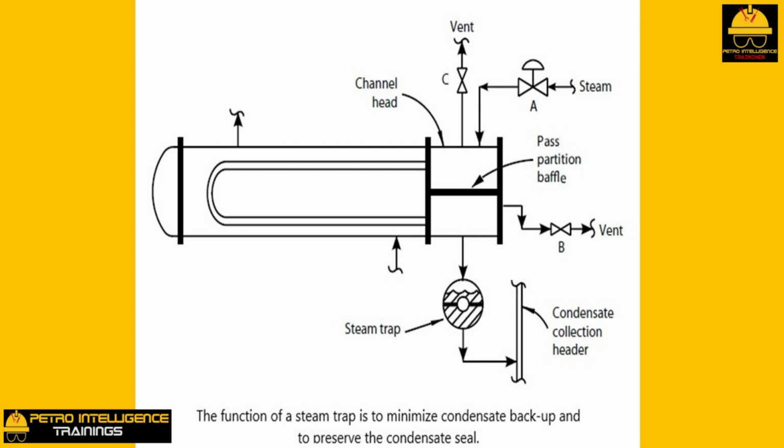The standard is to continuously vent 0.5% of the steam through a restriction orifice to purge CO2. Even if you are producing steam from demineralized water, just a small fraction of this rate of venting is required.